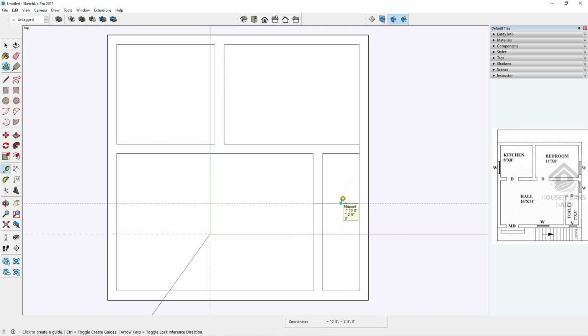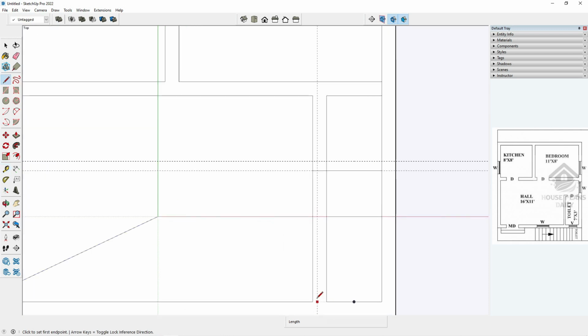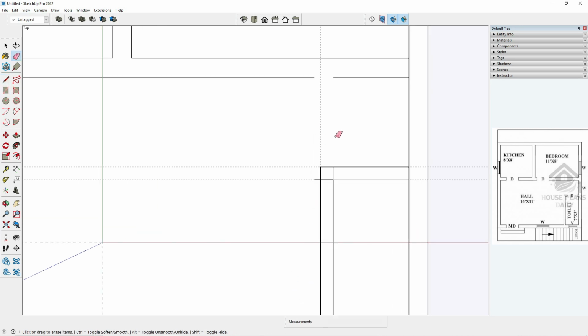And then an offset of 6 inch, because bathrooms usually have a 4 inch or a 6 inch wall, which will help you to save the space. Similarly, we'll be doing over here. What we have to do now is corrections. I'm going to draw this line over here, till here, and connect this. I'm going to erase this extra line from outside, this as well.